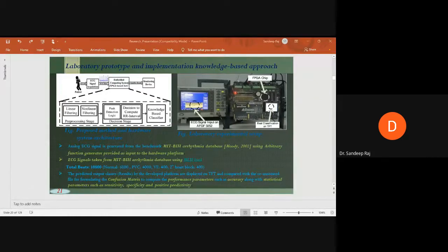So this is actually the architecture. If we see how this FFT-based DWT method has been implemented, we have first split the even and the odd index sequences. Then an n length FFT is performed on each decimated input. And 4 frequency domain convolutions are performed by multiplying the Hermitian symmetric matrix, which is the FFT of the input and the filter.